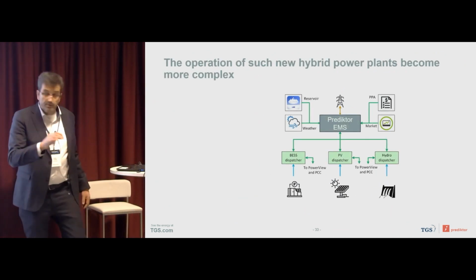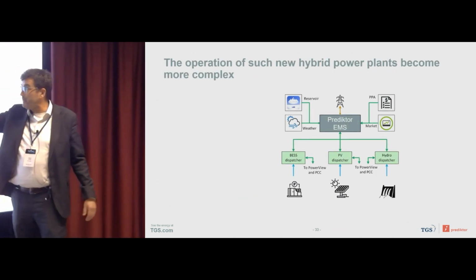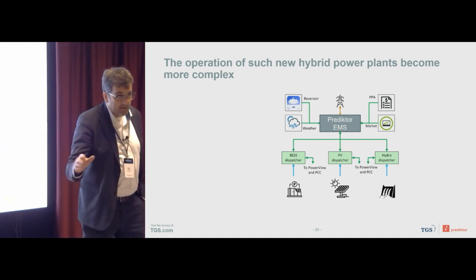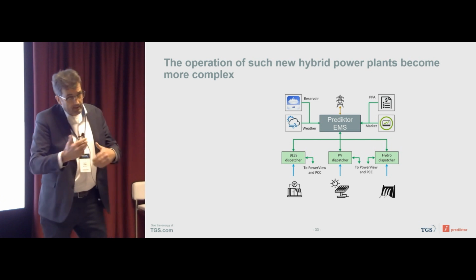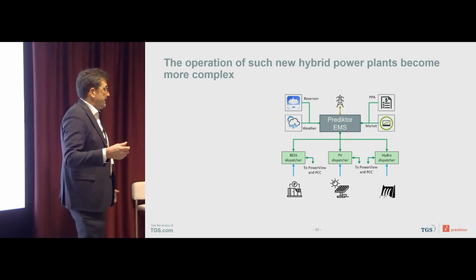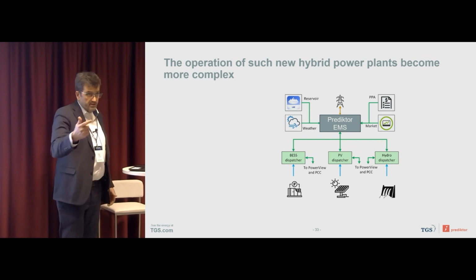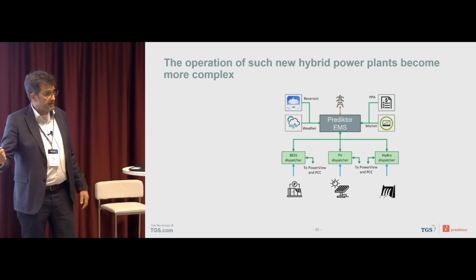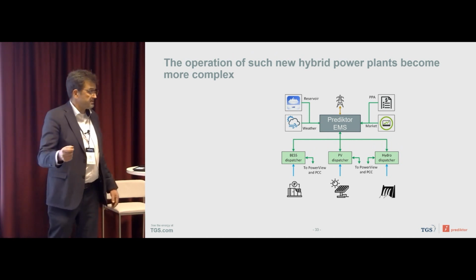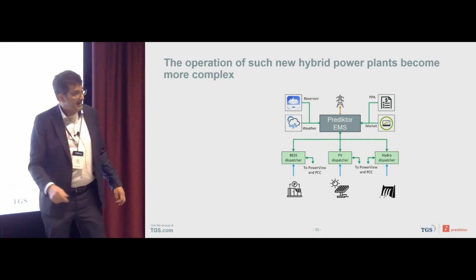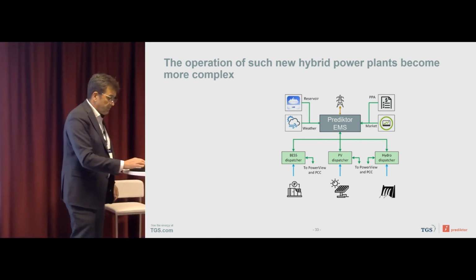And to operate this, we are now building and developing an energy management system that will do optimization in real time, taking into account the various limitations of the assets design-wise, and the predictions on the weather, the varying market conditions, and doing a model-based predictive control of each specific asset, and then doing dispatch to the controllers to run all the different assets optimally.